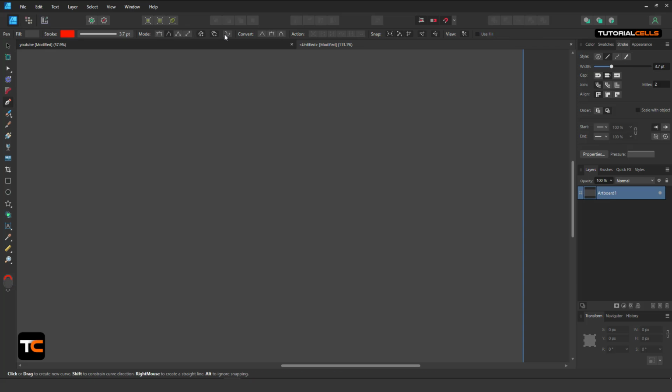Okay, another setting is an interesting one. Rubber band mode. If you create, as you can see, you cannot see the silhouette or the ghost of your drawing to where you want to position it. But if you activate that, as you can see, a ghost or silhouette of your curve. It means if you, for example, click here, your curve will be created in this position.